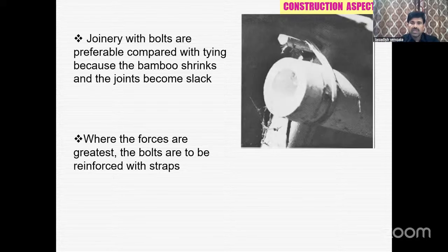This truss is connected to different beams and other trusses also, so the entire roof portion gets affected. The roof is connected to the columns. So what I mean to say is, if any of the joinery weakens, the structural integrity of the entire structure may be affected. Hence, you have to make sure there is no shrinkage in the joint.